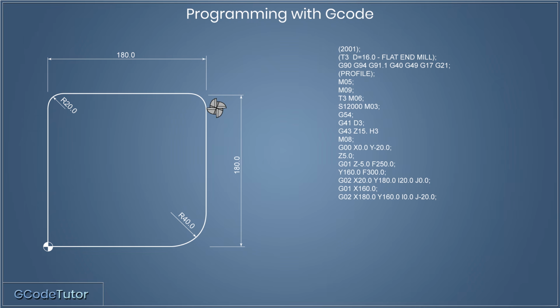So like before, this is the same size radius as before, by the way. We're still using a 20 millimeter radius even though it's not marked on the drawing. I omitted this dimension so it didn't get too confusing and too cluttered. I like to keep these drawings very simple when explaining G-code. So as we move along to this next radius, we have to declare the endpoint using X and Y coordinates and the center point of the radius using I and J.